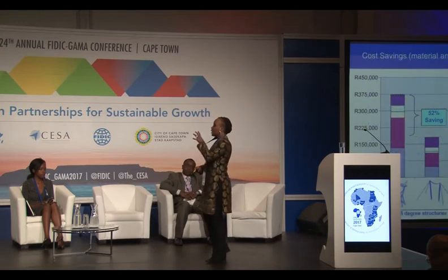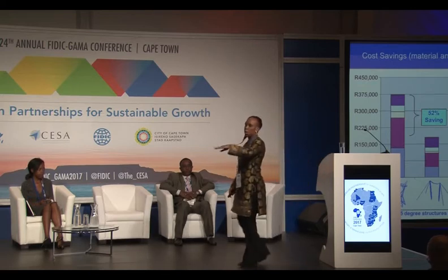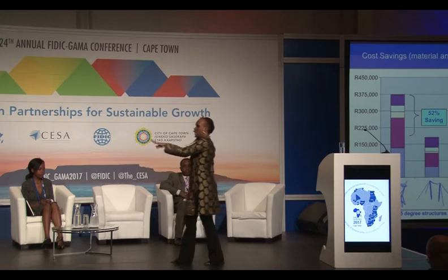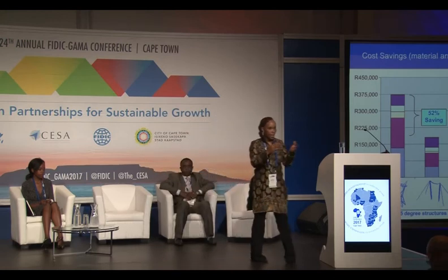So basically what this slide right here does is it summarizes the cost saving throughout the cycle. So in other words, the material that you need to build the line and actually the construction costs. And all it does here is it gives information on what you call a suspension tower. A suspension tower is something we use to just support the conductor. And then a strain tower is a structure that we use to actually change direction.